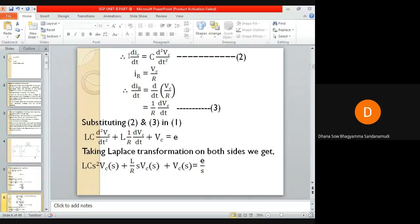Now you have got an expression for d by dt of IC and d by dt of IR. If you see in your previous equation number 1, you have these terms d by dt of IC and d by dt of IR. So substitute equation number 2 and 3 in 1. You will get L into C into d square Vc by dt square plus L into 1 by R d by dt of Vc plus Vc is equal to E.